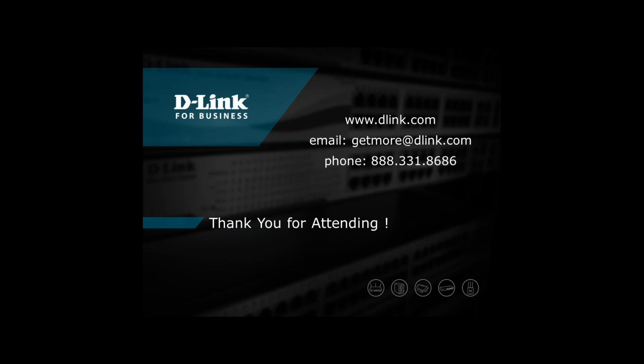The next question here: does POE impact gigabit transmission speeds? My answer on that is no. POE is a steady or constant DC power on the copper conductors, and Ethernet is ones and zeros, and they're coexisting on that copper, at least when we're using phantom power. But with the way that center tap transformers are used within the devices, these two things, the steady DC power and the Ethernet signaling, don't know about each other and don't impact each other, so I'm not aware of any cases where POE power would impact gigabit speeds.